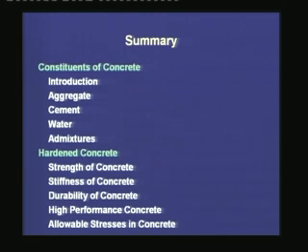Next, we moved into the properties of hardened concrete. The first property we studied was the strength, which is the primary requirement in prestressed applications. For the strength, we studied 2 types of strength, the compressive strength and the tensile strength, and we found that the compressive strength is quantified by a number called the characteristic compressive strength, which is based on a probabilistic distribution of the results,